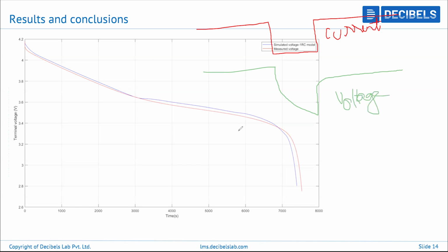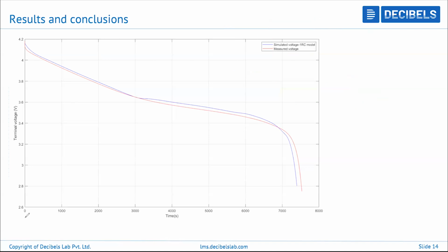This voltage response will be recorded once again from the measured data. From there, we can use it as a reference to go for cell modeling as well. And then we can see how close the PNGV model actually represents this kind of behavior, right? Of course, there are also more advanced types of modeling as well, where we can go for simulation in real-time scenarios where we have drive cycle inputs, and from there we can get outputs as desired. So this is the conclusion that we make for this PNGV model.